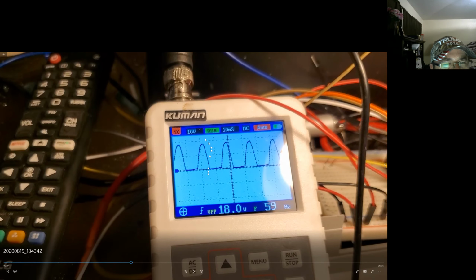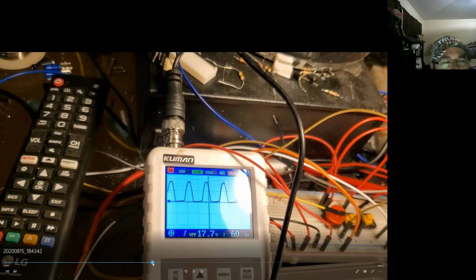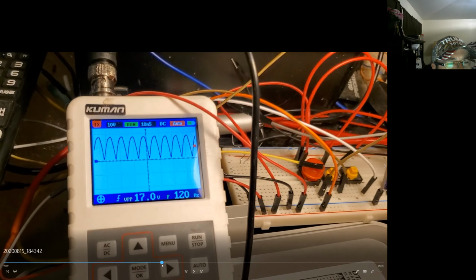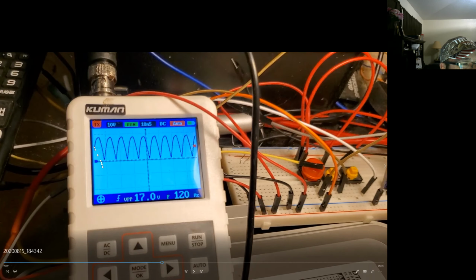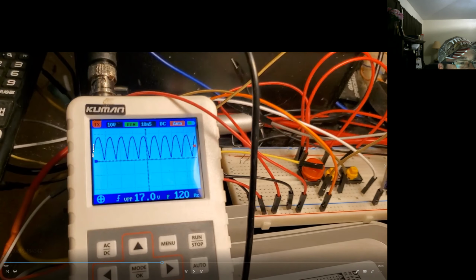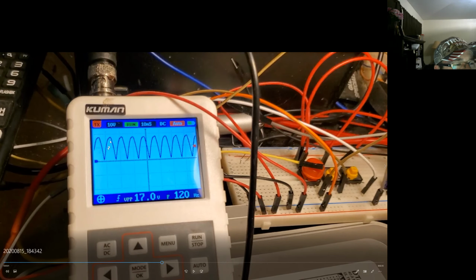Here's that half, the sine wave's going like this. And then if you go through the full wave, boom, you get this. You're inverting the negative ones, which were right here. You're flipping them, using 2 diodes. It's basically like taking 2 9-volt batteries, doing 9 volts and then flipping the other. So the pulses that were down here are flipped up here. Now this is one cycle of your sine wave, and you get 60 of these a second. So you're going to get 120 of these pulses every second. Boom, boom, boom, boom. And then you have this gap.